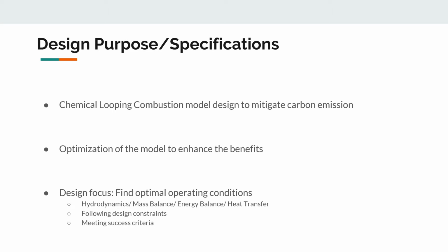Within these areas, the design focus will be determining the optimal operating conditions, process setup, and direct measurables such as solid conversions and the input-output mass flow rates. Our design constraints are based on the proposed model to reiterate the working model to optimize. We will be operating at 1000 Kelvin and 10 bar with the most efficient oxygen carrier while meeting the health and safety protocols of the CLC process.